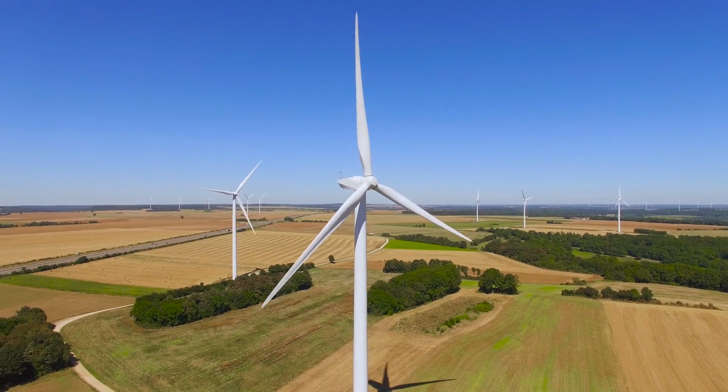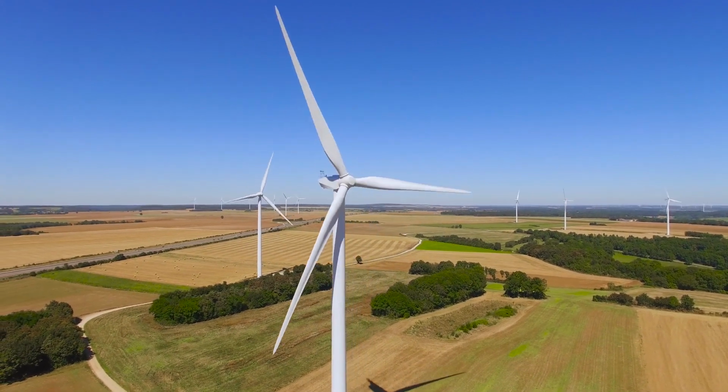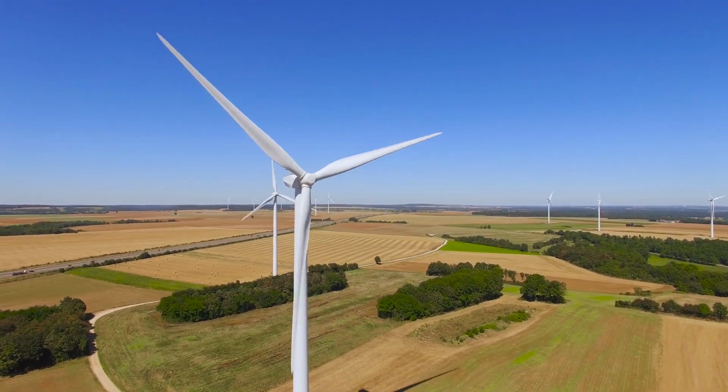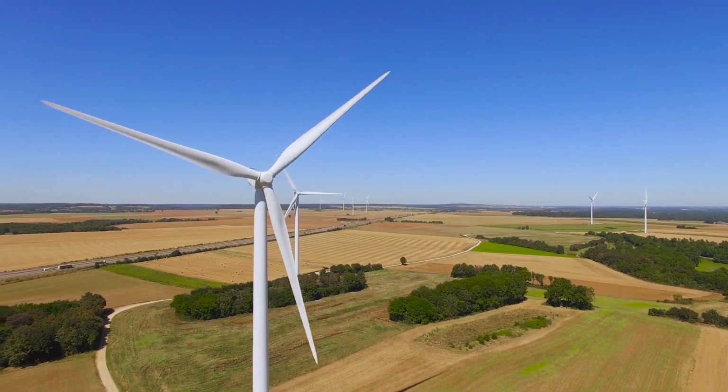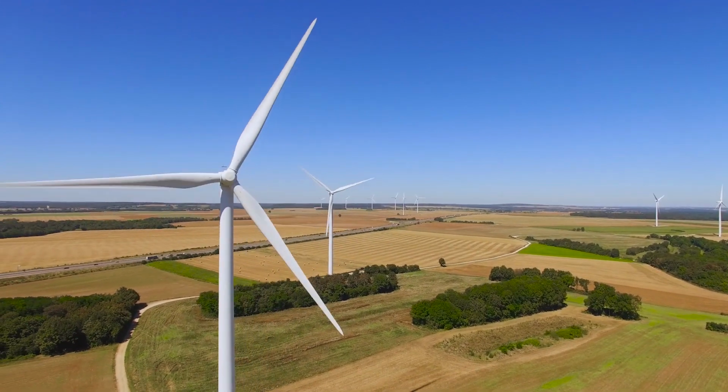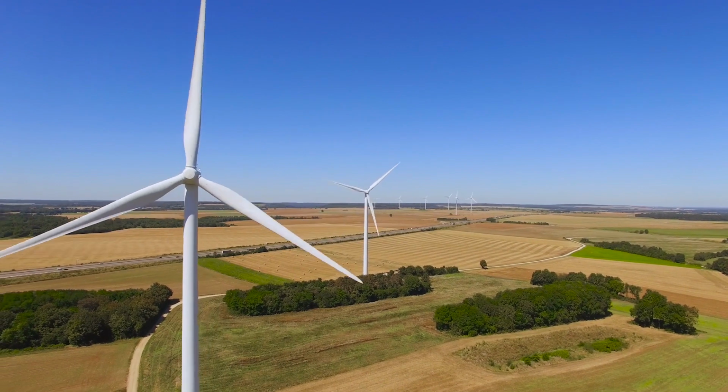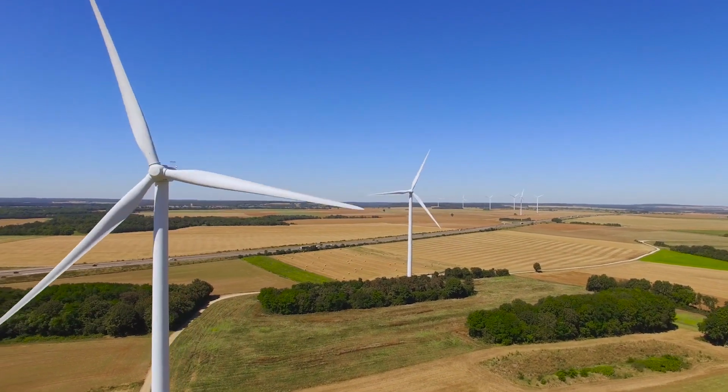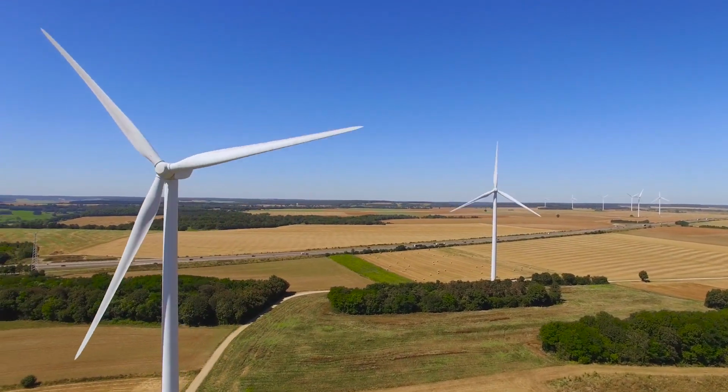Now, we will talk about the limitations of wind power. Power density is very low in the case of wind energy, so it needs a very large number of windmills to produce modest amounts of power. Cost is very high because the wind turbine technology mainly comes from abroad, and presently we are working on the cost issue in India also, to reduce cost.